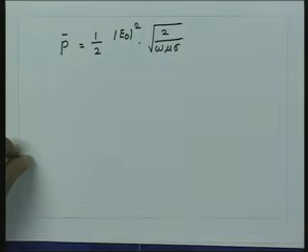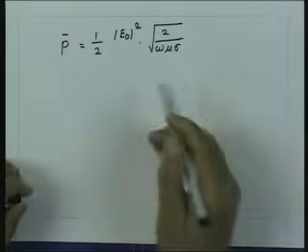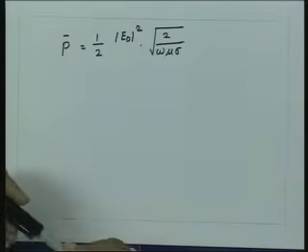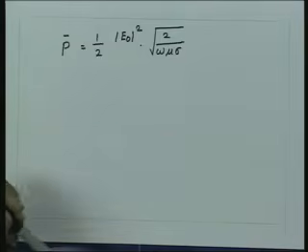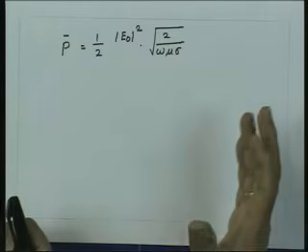So, this expression is exactly same as what we have got from our surface impedance calculation, the power loss. So, essentially we can calculate the power loss either by using the circuit concept, like find the conduction current density, then you find out the ohmic loss, which is I square R loss, or you can use the wave concept to find out what is the power going inside the surface of the conductor, and that power essentially should get lost inside the conductor, because the field at z tends to infinity essentially goes to 0. That means there is no power flow at z equal to infinity. So, whatever power has gone inside the conductor must have been lost in the heating of the conductor.